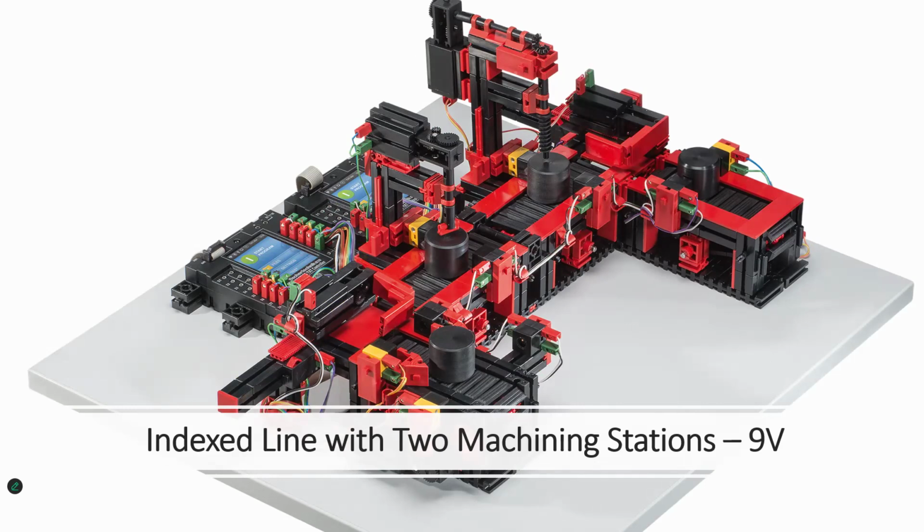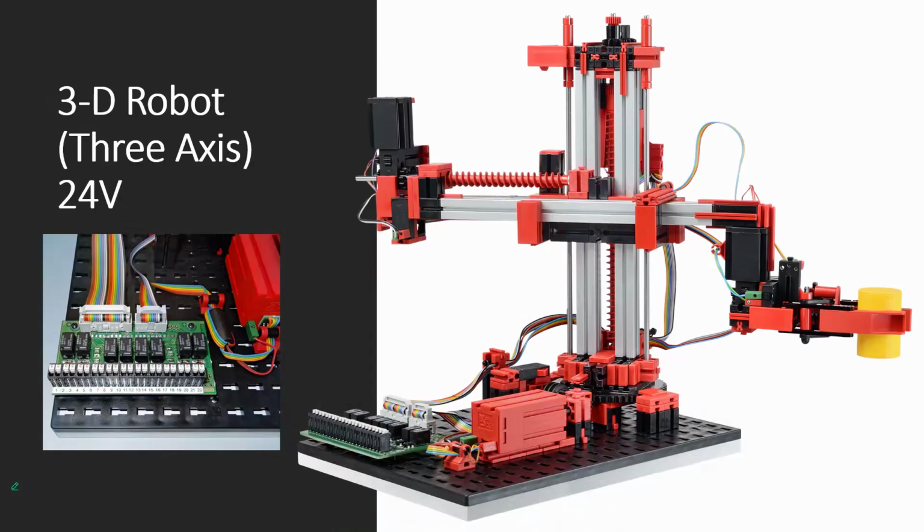The next up that we're going to look at is a variation on the idea of a pick-and-place robot, which is the 3D or 3-axis robot. Now, the 3-axis robot has gripping forceps, which it uses to help it quickly and precisely position the workpieces that it picks up in 3-dimensional space. The degrees of freedom for this robot are as follows. Axis 1 can turn 180 degrees. Axis 2 can move forward or backwards 90 millimeters, and Axis 3 can raise or lower 150 millimeters.